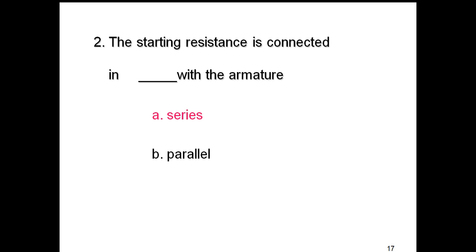Yes, the answer is option A, series. When we connect this in series, the resistance gets increased, then the starting current gets limited.